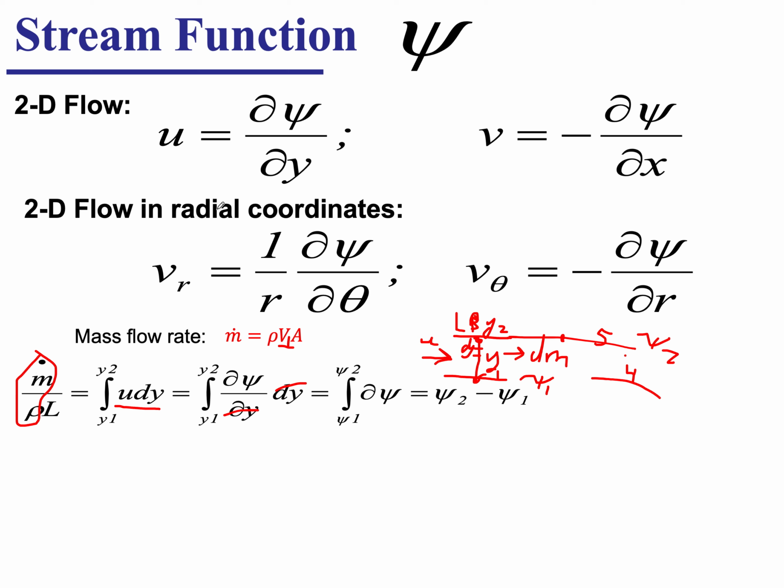And we covered it in a different way. We said if I have two streamlines, in one location our streamlines were separated by a distance L1, and another location by a distance L2, then our flow here is going to be faster than our flow at this location, primarily because the mass between two streamlines is conserved. And that's what this also tells us. And then we can do the same for a flow going purely vertically.